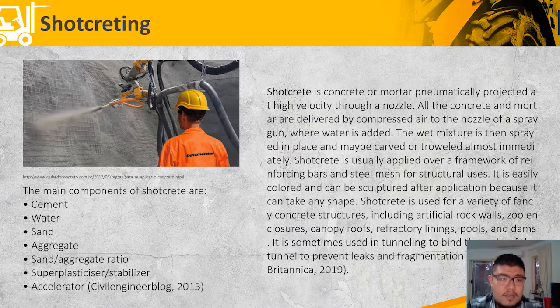And this is the third type, which is shotcreting. The main components of shotcreting are cement, water, sand, aggregate ratio, superplasticizer, and stabilizer accelerator. So shotcrete is a concrete or mortar pneumatically projected at high velocity through a nozzle.